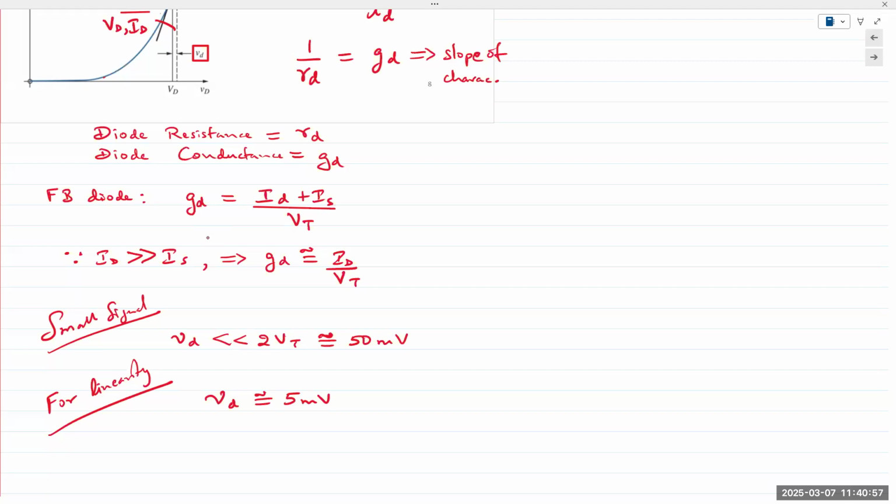Even a 5-volt signal or even a 1-volt signal can have infinite values, any kind of AC waveform. And so it's constantly changing value. You can take 1 millivolt steps, you can take 0.1 volt steps, but it's changing, right? So for every change, we can describe the diode resistance. So basically, this will describe how the diode will oppose any change in the input signal.